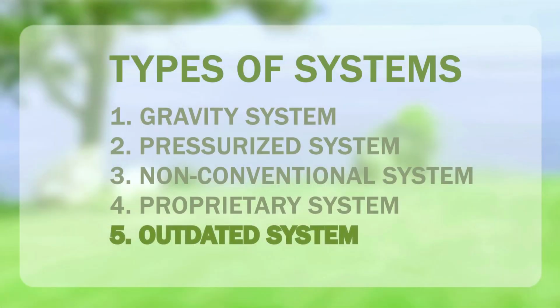So, in general, as soil permeability and depth to a limiting layer decreases, the complexity of the system increases. So do the cost and maintenance requirements. Non-conventional systems cost 2 to 3 times more than your basic conventional system. It's important to protect the system you have because replacement septic systems can be very expensive.